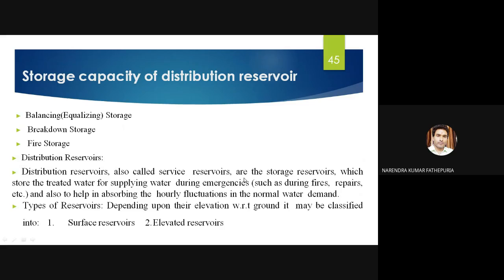Distribution reservoirs, also called service reservoirs, are the storage reservoirs which store the treated water to supply water during emergencies, such as during fires, repairs, etc. And also to help in absorbing the hourly fluctuations in the non-supply of water.